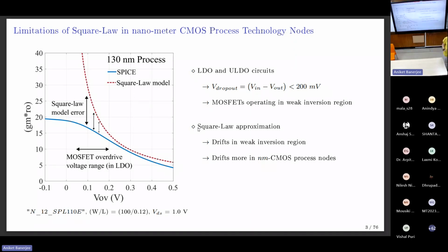So imagine a scenario where I'm designing a differential amplifier or an OTA, any analog circuit. I start crunching numbers with square law. I take the aspect ratio, or W by L, that comes out of my hand calculations and put that all in. And then I run the simulations only to see, oh my God, this is way off. Underlying way off.